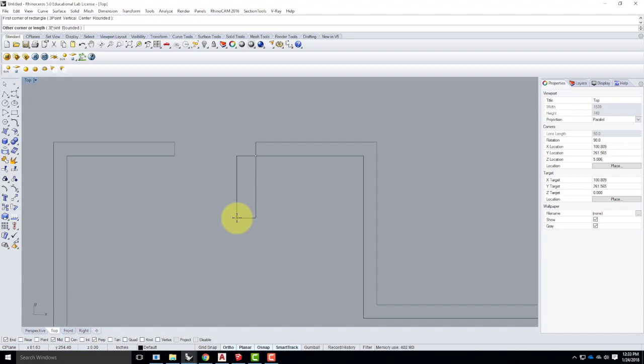So in this case, I want to go at, so relative to where I started, I want to go negative 1.75 inches, which is 1 3/4 inches. That's an exterior door thickness. You can use round numbers. I'm not going to double check. And I know that my door is 3 feet long. So I said at negative 1.75 inches, go negative in the x direction by negative 3 feet, going negative in the y direction.